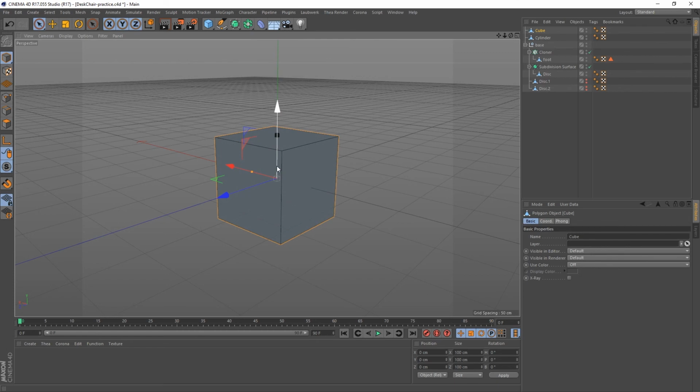And now when I hit the Enter key, it'll go into edit mode. So instead of Tab, you hit Enter. Tab for Blender, going into this mode. Now you've got the point mode, line mode, or polygon mode here, the point, line, plane. The quickest way to switch between those is to hit the Enter key again. So every time you hit the Enter key, it'll go to the next one. And it just goes round robin.